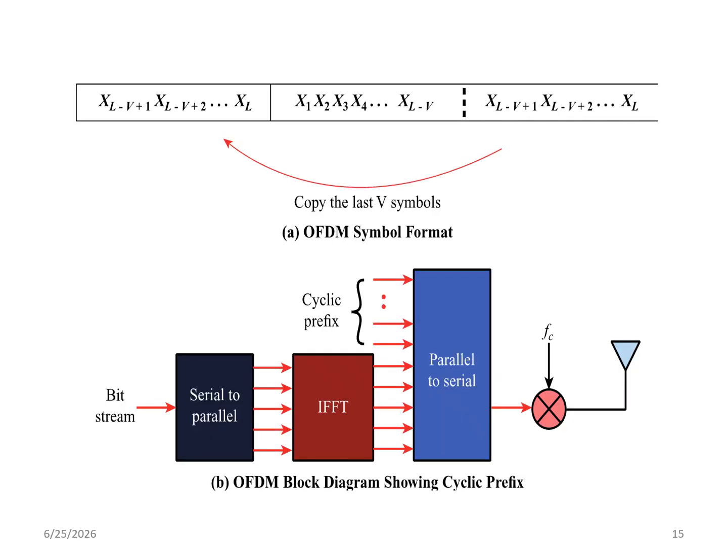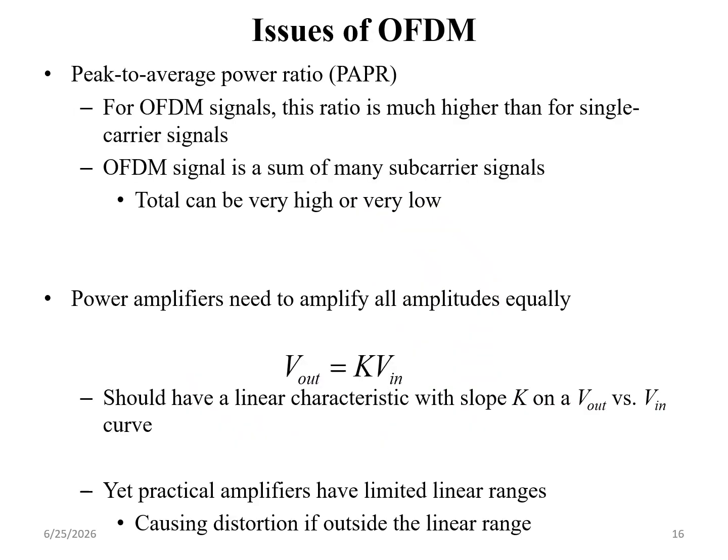Okay. Serial to parallel, IFFT, parallel to serial, adding cyclic prefix. Then we go for analog to digital conversion. Then we go for transmission.